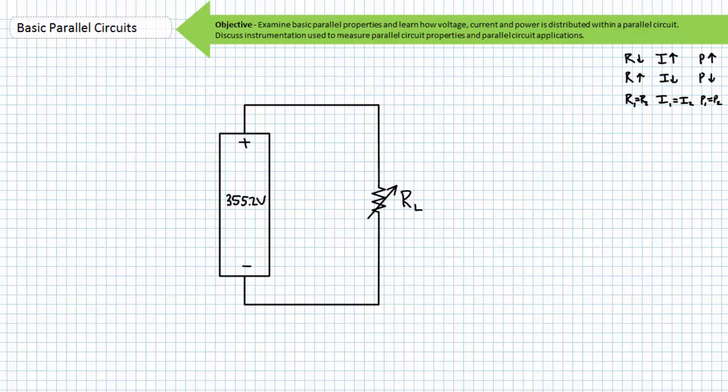Provided each electrical source is of the same voltage, the addition of electrical sources in parallel simply increases the available power output by increasing the amount of available current. Allow me to demonstrate. Consider a string of 96 3.7 volt lithium-ion batteries in series with one another. Each battery is limited to supplying, let's say, 105 amps.